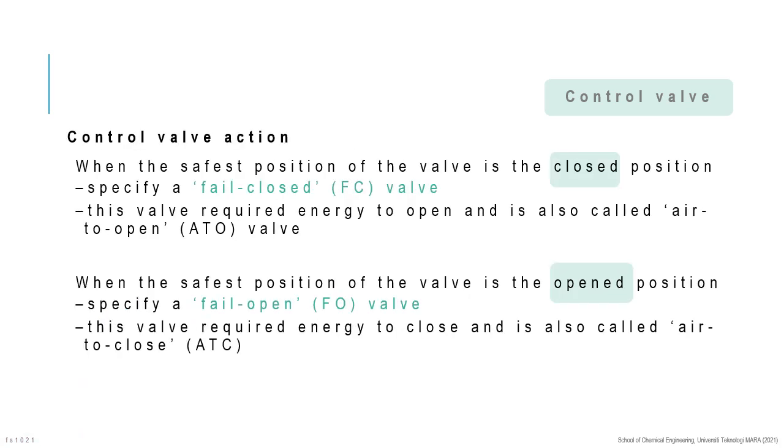In real practice, there are possibilities when the energy supply fails. As an engineer, what do you want the valve to do when the energy supply fails? This question concerns the fail position or action of the valve. So the main consideration as an engineer is safety.